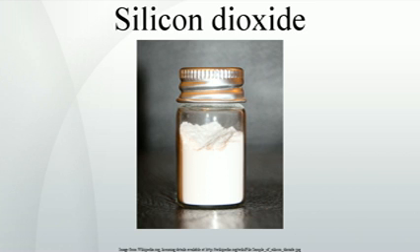The change in the coordination increases the ionicity of the SiO bond. But more important is the observation that any deviations from these standard parameters constitute microstructural differences or variations, which represent an approach to an amorphous, vitreous or glassy solid. The only stable form under normal conditions is α quartz, and this is the form in which crystalline silicon dioxide is usually encountered. In nature, impurities in crystalline quartz can give rise to colors, see list.